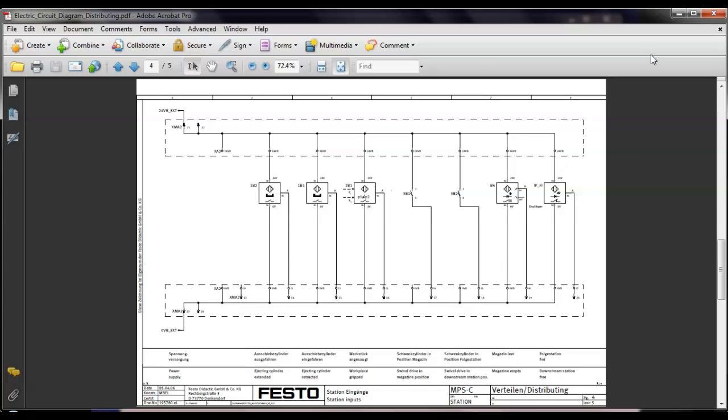So, like I said, some PLCs you don't have that option. Our PLC here, if you look at the top, we've got two commons. It does not say plus, it does not say minus. So what we're doing is setting up a common for the PLC. I have a minus running to both of the commons, so that means I set that PLC up to be sinking. On this one, the first one is like 5 inputs, I think I can set up one way.